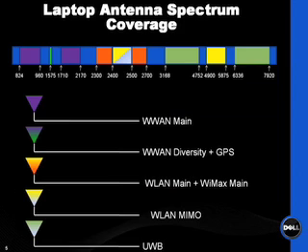Then apart from this, now in the laptops we are going to put UWB, like a wireless USB, so that like a docking station, suppose you want to run some video, you can just wirelessly stream all the videos. So that is UWB. In UWB also, initially it was only band group 1, but now we are also going for band group 3. Just to give an idea for the people who are away from UWB, we don't use band group 2 in UWB because band group 2 interferes with the wireless LAN frequencies.